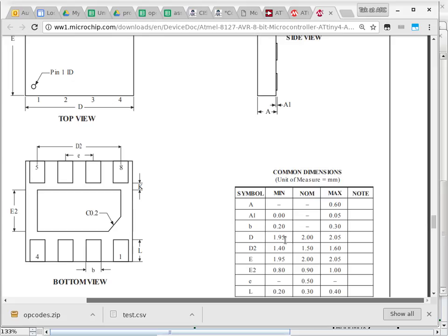In 1990, which is really not that long ago, right? It's only close to 30 years ago. So close to 30 years ago, what we can do with a 2mm by 2mm chip required a circuit board about this big. And that had a power consumption of close to 200 milliamps. This is 200 microamps. In other words, a 1,000-fold power consumption difference. And this has more processing power. It has more devices that are built into the device itself.